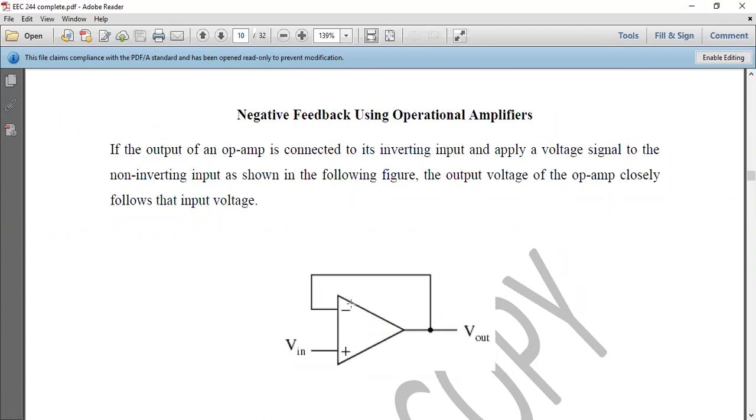Anything that comes into this inverting input, the amplifier will ensure that if you are supplying a signal from that point, the signal will be amplified based on the difference between the two terminals, minus and plus. It will check the difference between the two terminals. Whatever the difference is, it raises it up by the value of the gain. Meanwhile, if the input is entering from minus here, the amplifier will make sure that the result is inverted in sign. That is to say, if you are sending in positive voltage from minus here, the positive voltage will be amplified, then turned to negative at the output here.